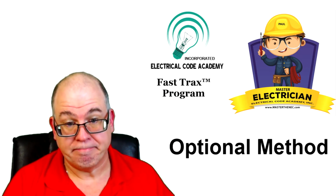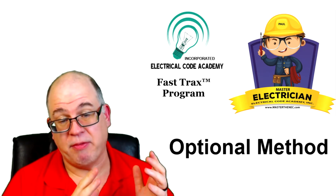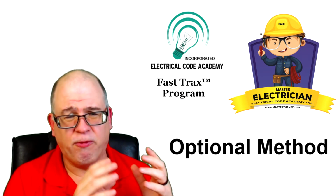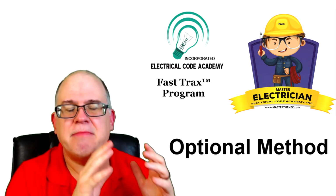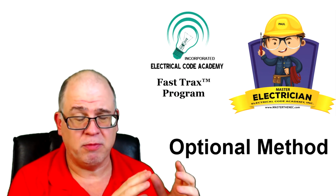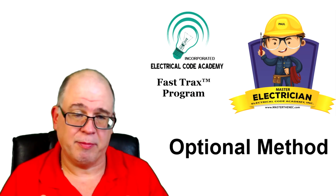Maybe that's what I'm doing. And so maybe I'm in that panel and maybe I don't have a main breaker out there. Maybe I'm trying to comply with the 6 disconnect rule and I'm only using 2 of the 4 spaces, or 2 2-pole spaces. I don't know. But the point is, I'm out there and I'm not handling 100% of the load because some of the load is out there in that panel. And now when I go to feed the panel inside, it's handling some of the load.